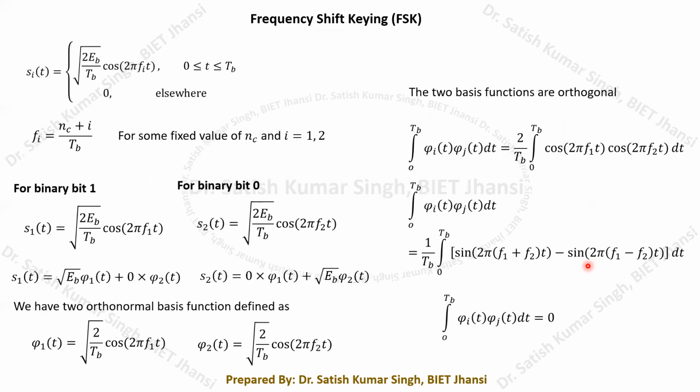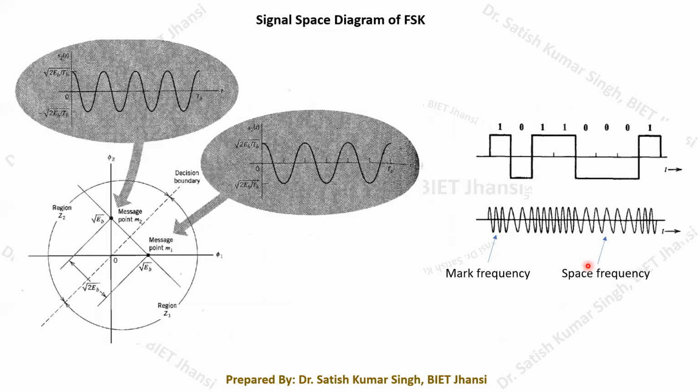I just wanted to make one point here about frequency shifting. In the introduction, I explained that in the case of an FSK signal, it is based on this particular bit sequence. Whenever we have a bit equal to 1, one particular frequency is sent, and when we have 0, another frequency will be sent.